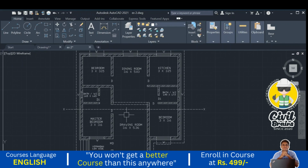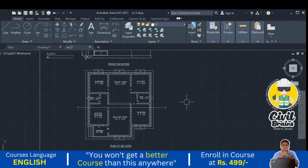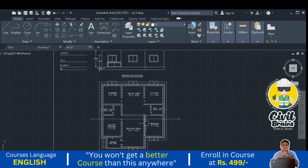First thing we need to identify is where the section line is passing. Wherever this section line passes, in that place we need to show the section. One more thing: the section line will be passed through the most critical cases, where most of the information will get covered. Here we simply pass it over here, but we can provide it here also, or else we can provide the section like this also. I can show you.